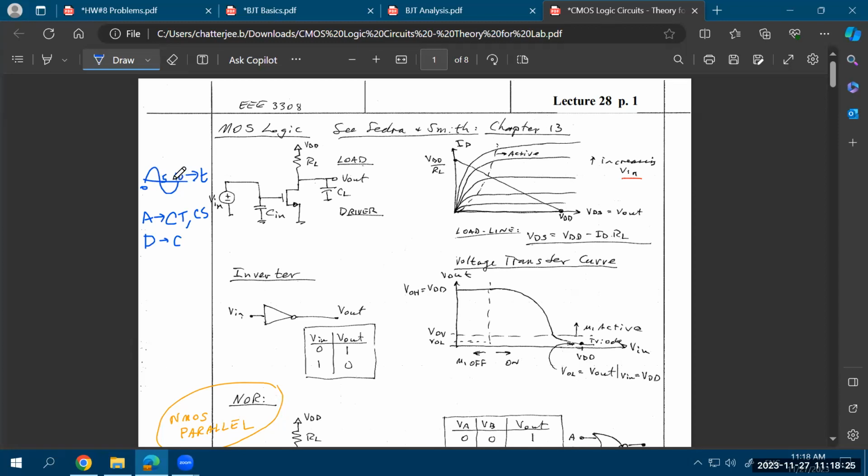So over this entire 10-second time duration, you have the full sine wave. Now, if you sample each second, that is, every second I want to find out the value of my sine wave, your first sample would be somewhere over here. The second sample will be at 1 second. And by sample, I mean what you mean by samples in traditional English, that you're just taking samples of the signal at every second. You're taking the value of the signal at every second.